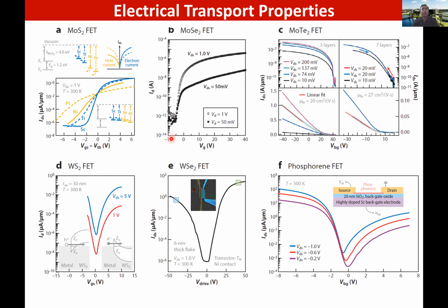And experimentally, you can get different types of 2D materials. Some of them would be a P-type material. Some of them are going to be N-type. So this is an N-type molybdenum diselenide. This is a P-type molybdenum. Obviously, I don't have to tell you why I'm calling them one N-type, one P-type, because I'm looking at the current versus gate voltage characteristics. Okay, and I'm sure you're familiar with this kind of characteristics from your MOSFET courses.